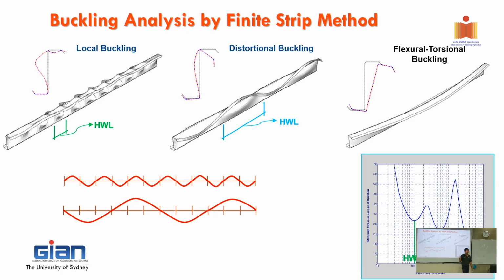So that's the second mode, right? So you understand now where it came from. Now the last one is the other one, elastic buckling. The whole section will buckle sideways and twist because it's subjected to the elastic buckling of the whole section. Right, so that is somewhere in here. And that will answer your question, depending on the length. The halfway length will go up and down. The longer it is, the lower the buckling load is, right?